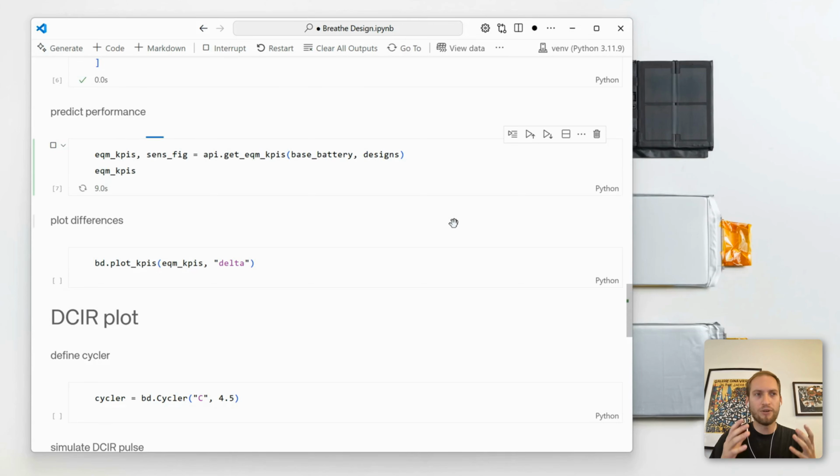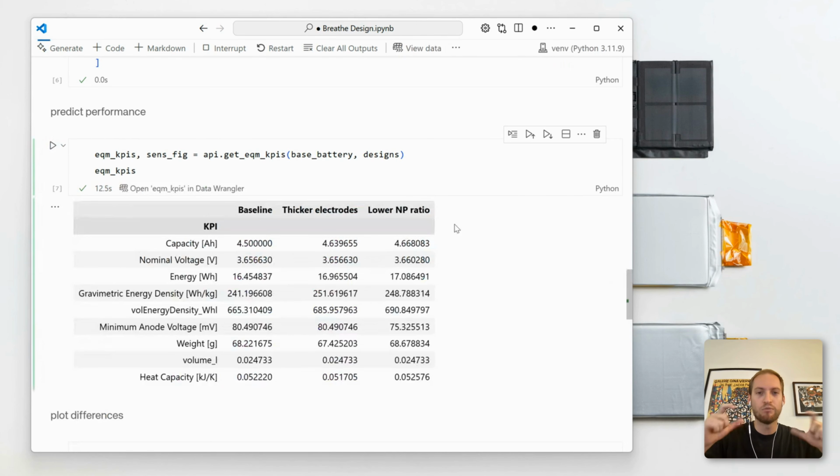And if you only increase the electrode thickness of your model, but then thought about conceptually rolling up that jelly roll to put it into a can, if you're rolling up a thicker electrode, it's not going to fit in the same size. And that's one of the really powerful features of Breed's equilibrium model: when I increase the thickness of that electrode, it's actually going to decrease the overall length of the jelly roll to keep it consistent. So we call this physical consistency. And so when I virtually roll up that jelly roll, it will still fit perfectly into that 21700 cell.